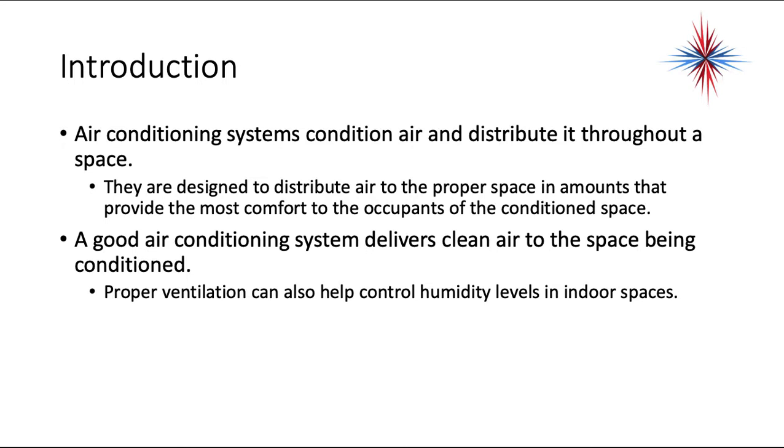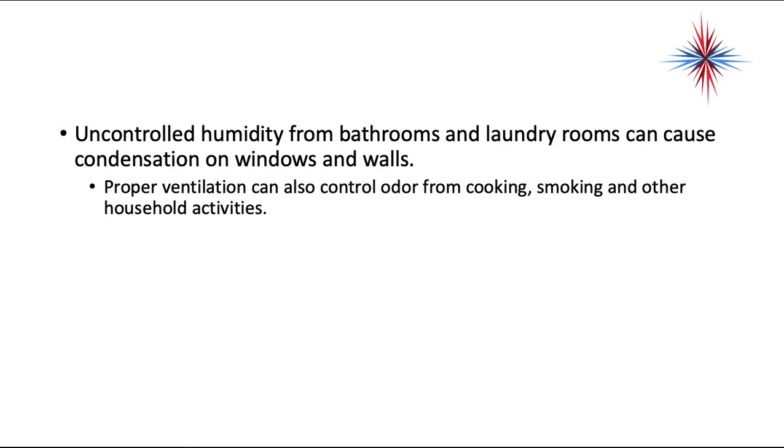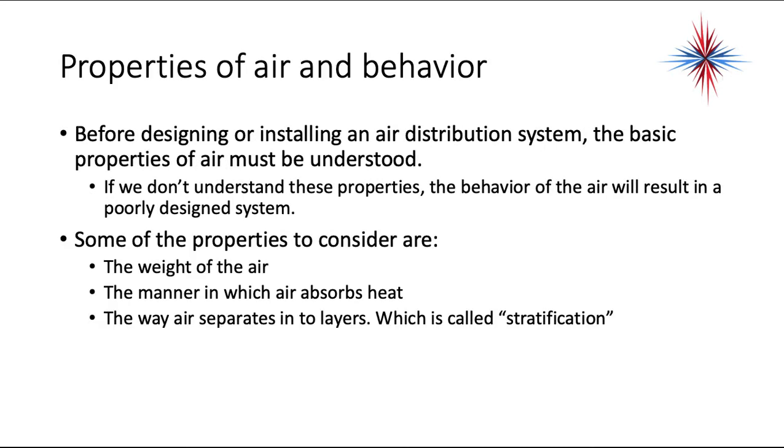A good air conditioning system delivers clean air to the space being conditioned. Proper ventilation is also important because it can help control humidity levels in indoor spaces. Uncontrolled humidity from bathrooms and laundry rooms can cause condensation on windows and walls. Proper ventilation can also control odor from cooking, smoking, or other household activities. So you can't have a building without ventilation. Ventilation has to happen, and in most jurisdictions, ventilation is code now.